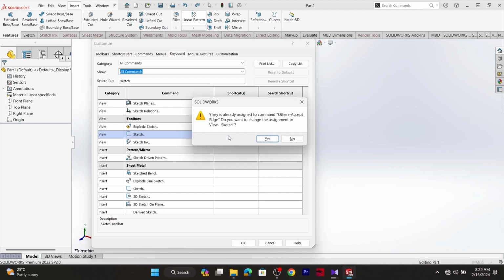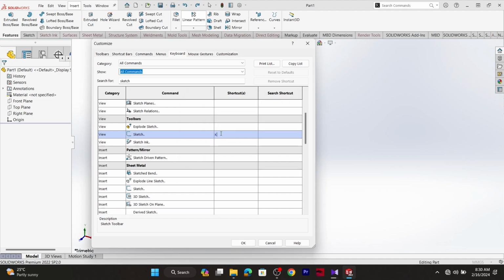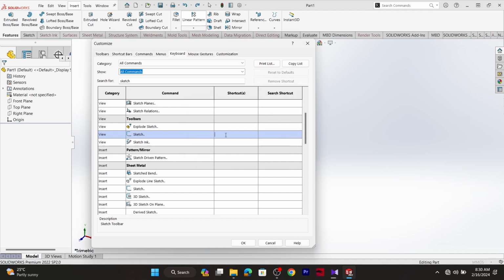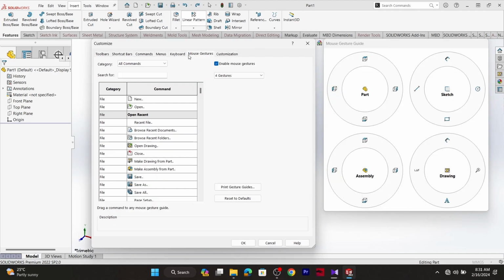Now you can also assign a combination of multiple keys, for example Ctrl K, and for that simply press and hold Ctrl and then K key and it will assign that. Obviously it has assigned K Ctrl K, which is not kind of a command that you would want to use, and also Ctrl K is assigned to something else, so we don't want that. I'll just cancel it out, delete everything, and then I'll assign, maybe Shift K. And yes, that's empty, so it will assign that key. In this case, I'm not going to make any customization, so I'll just delete this.